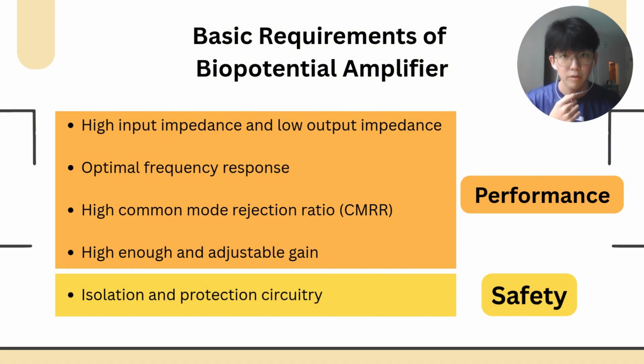In terms of performance, we need to have high input impedance, low output impedance, optimal frequency response, a high common mode rejection ratio, and high enough and adjustable gain of the amplifiers. And in terms of safety, we need to isolate and also protect the circuitry.